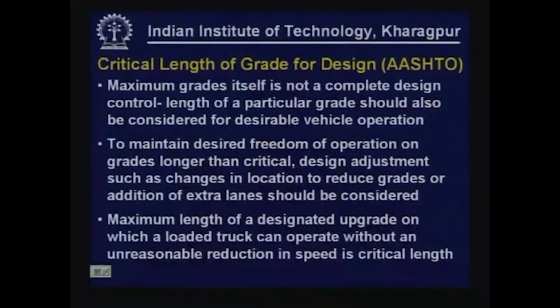Now, wherever it is difficult to maintain the freedom of movement or the freedom of operation on grades longer than critical, obviously, there will be loss in freedom of movement. Therefore, suitable design adjustments, such as changes in location to reduce grade or addition of extra lanes, should be considered.